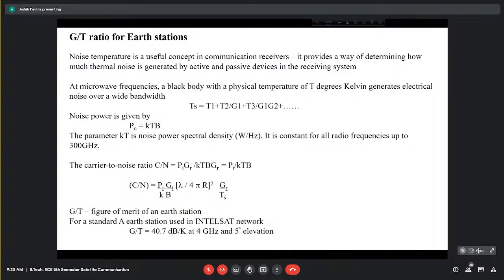These are small things which you should have learned in your communication classes, but they are equally applicable for satellite communication, because as soon as the linearity of the signal is disrupted by passing it through a square law detector, there are additional frequency components, for example, the square of a frequency.